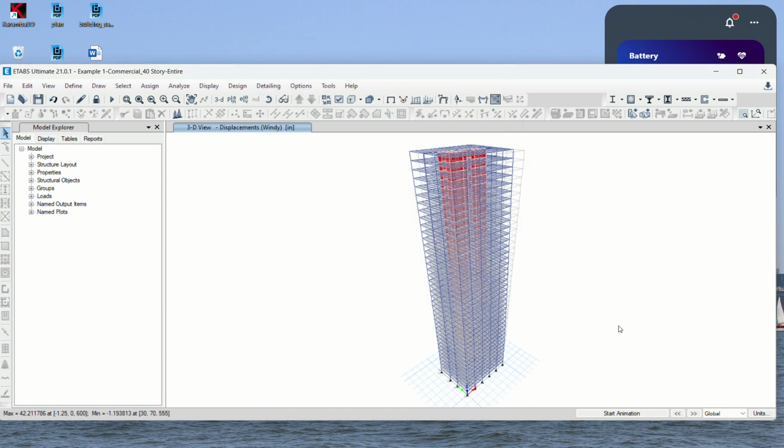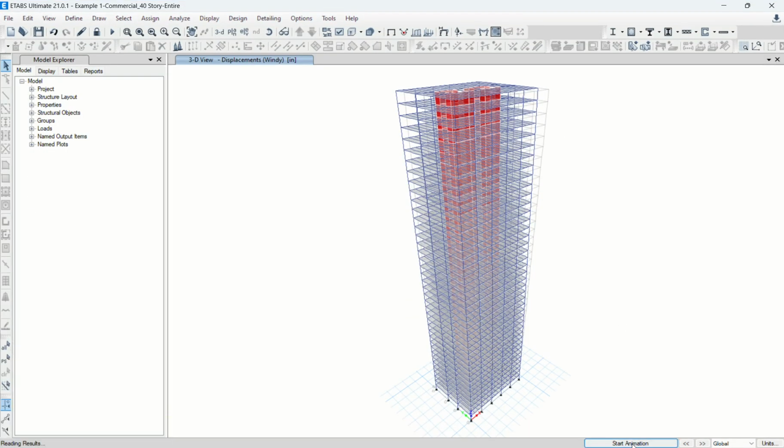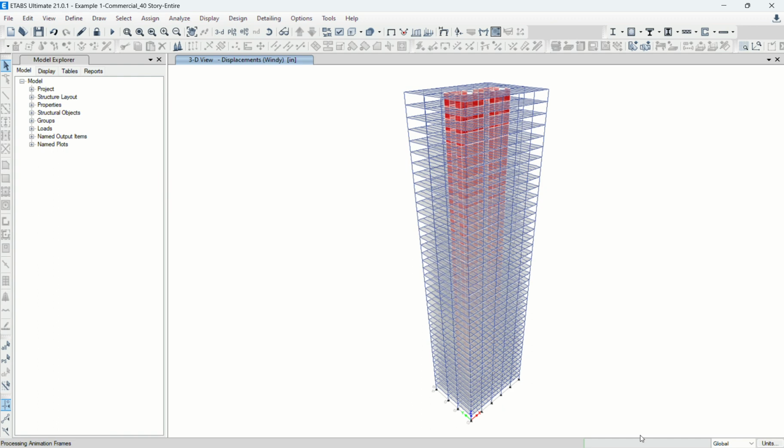This is something that at the beginning is how we verify our input and associate output. Geometrically, everything is connected. It looks like the column load takedown and actual force diagram look right. Deformation shape: wind X is actually blowing in X, so the building moves in the X direction. Wind blowing Y makes the building move in the Y direction. So we're just checking gravity graphically. Visually, we can see it much more clearly.